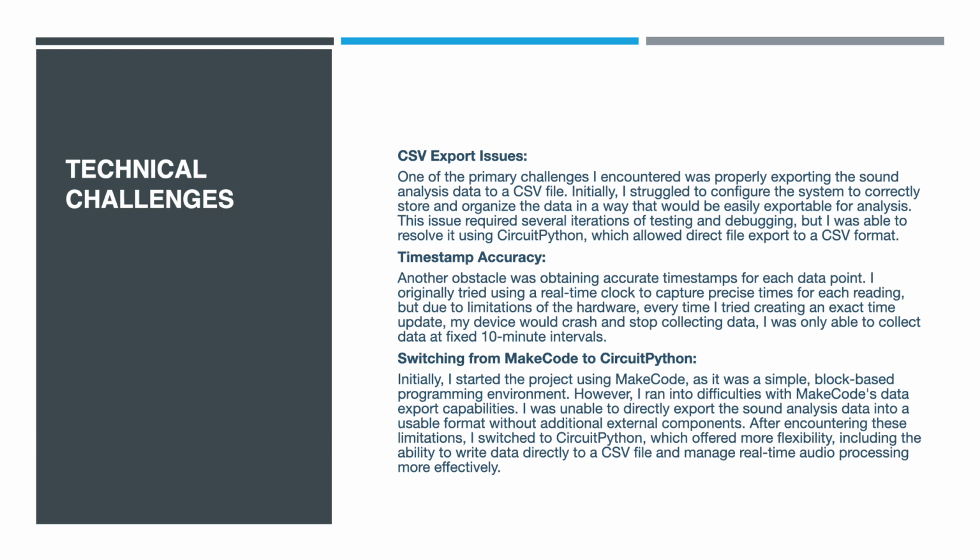The next thing was the timestamp accuracy. One thing that I kept struggling with was when I was trying to initially start this project, I was trying to record minute by minute, which in turn was causing my actual program not to run on my device, and basically my device kept crashing and would stop collecting data. I believe it was because it was just too much data to actually be able to handle. One other thing was trying to use the real-time clock to capture the noise precision for this time, so I had to actually set that as well.